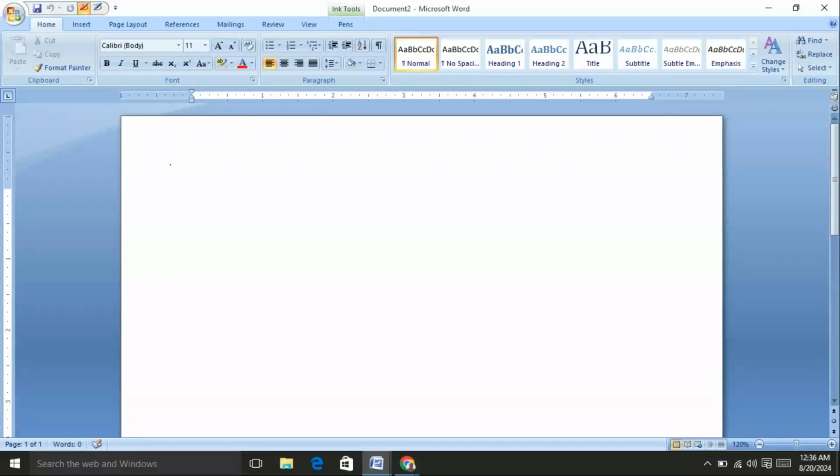To discuss the design of a 4-bit shift register. We already know what the shift operations are and how they can be performed. Here we are designing a 4-bit shift register. To design this register, I am going to use 2 by 1 multiplexers.